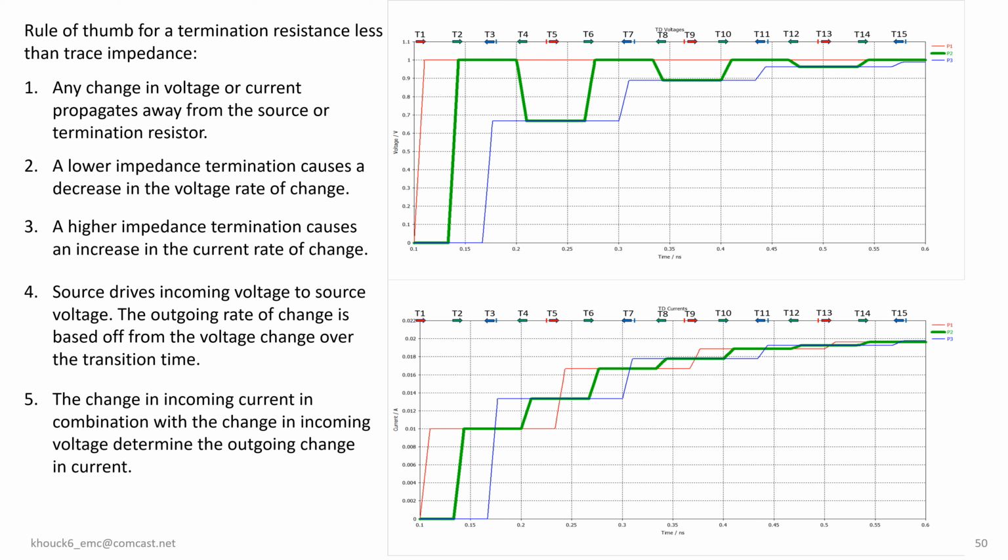At T3, Rule 2 comes into effect as the incoming rate of voltage change decreases owing to the lower value of the termination resistor. Simultaneously, Rule 3 becomes relevant as the rate of current change increases due to the lower value of the termination resistor. At T4, the changing field waves cross the midpoint originating from the termination resistor. Rule 1 applies.